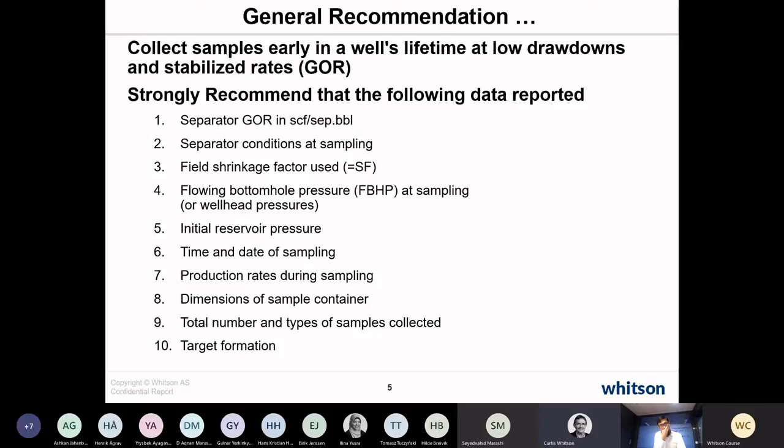So you'll need either a swelling test for gas injection, or, for a reservoir with compositional variation, that's gas cap in the top and oil in the bottom and varying GOR from top to bottom, you'll need multiple samples from top to bottom, and you'll need to get PVT data from each of those samples so that your equation of state is predicting not only that one oil at the bottom, but the intermediate oil, the oil at the gas oil contact, the richest gas condensate, and the leanest gas condensate.